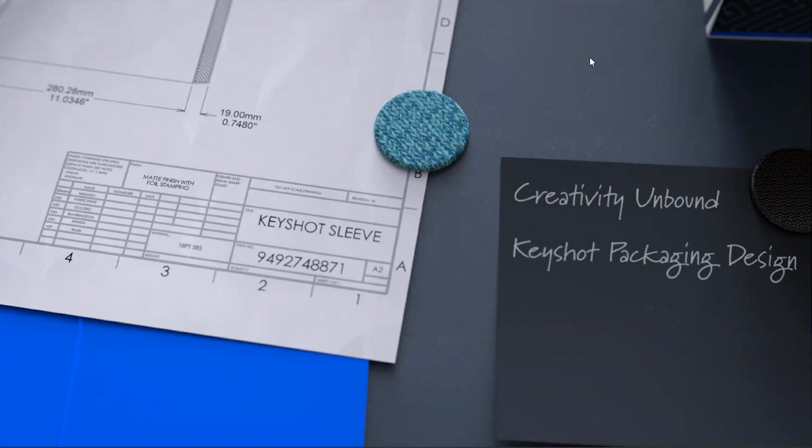I don't know if you can actually export Artios animations into KeyShot. I'd have to look into that. But what I'll usually do, when I build my Artios files and export them, is export a closed box, an open box, a flat box. I'll export all the different states I want, but then I wouldn't necessarily animate it in KeyShot. If you're going to animate the box, you might have to build it in different programs, because a lot of times when you export out of Artios, it'll export hundreds of faces. So it'll just make it a little difficult.